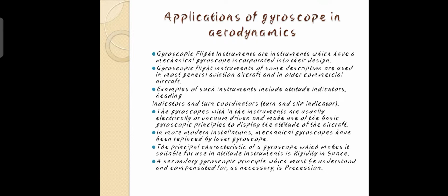Examples of such instruments include attitude indicators, heading indicators, and turn coordinators, turn and slip indicator. The gyroscopes within the instruments are usually electrically or vacuum driven and make use of the basic gyroscope principles to display the attitude of the aircraft.